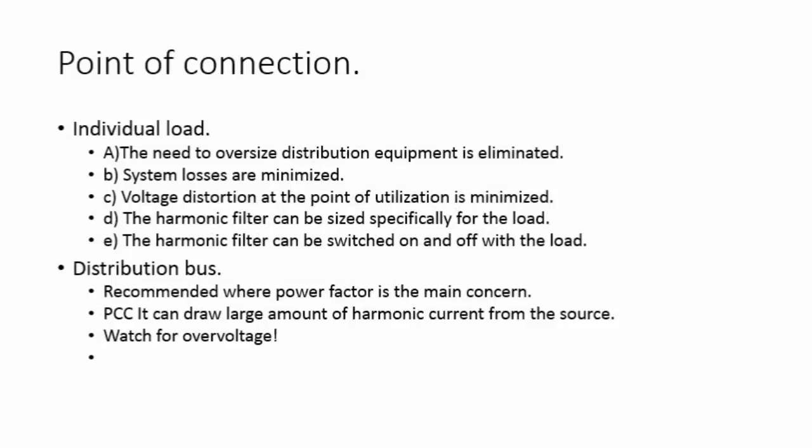You also want to watch out for overvoltage, because if you're in a utility ring where there are many customers, and those customers each has a filter or a capacitor at the PCC, you will have an overvoltage. And if the load of any of those plants goes out, the overvoltage will be more severe. So I guess that's it. That's the end of the IEEE standard. We're lacking the medium voltage, but it's not the scope of this webinar.